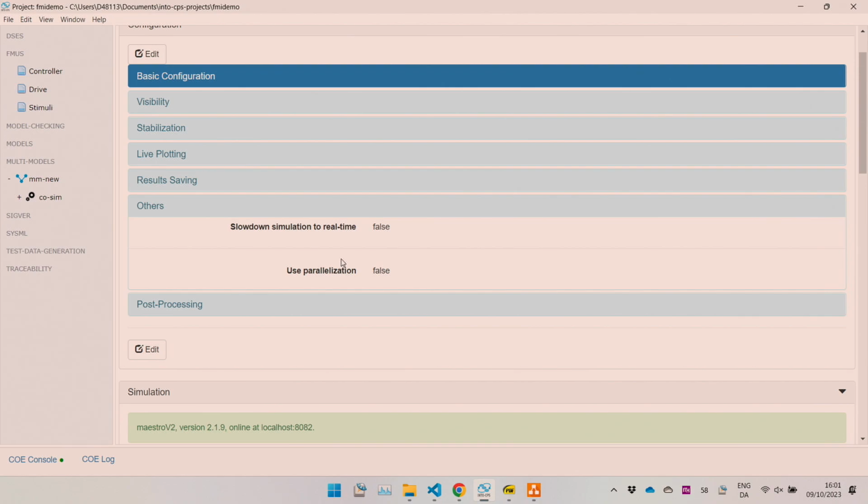They should approximate. This is expensive because you then have to reinitialize internal solvers. If this is a higher order solver, then it takes very slow steps and so on, and this slows down simulation. So you should make the communication step as large as possible, but small enough that you get enough accuracy.